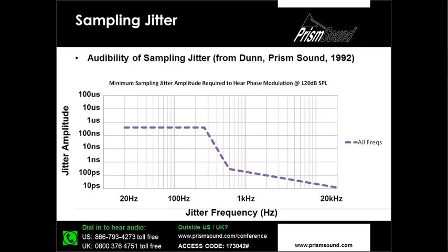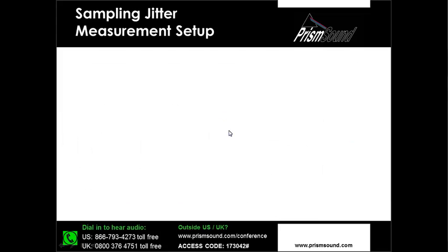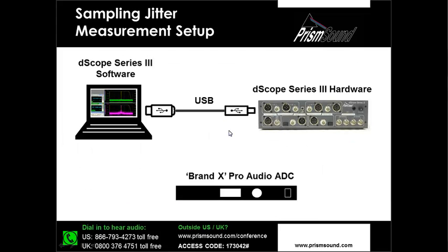And in that same paper that I just showed to you, we also derived some maths that allowed us to calculate the implied jitter performance at the converter by looking at the output spectrum of the converter device itself. And I should stress, and I'll probably repeat this later, that you have to be absolutely certain that what you're looking at is an intermodulation sideband caused by jitter before you can use these mathematical tools in a valid way. But that being said, let's just talk about, again, how we're going to measure this.